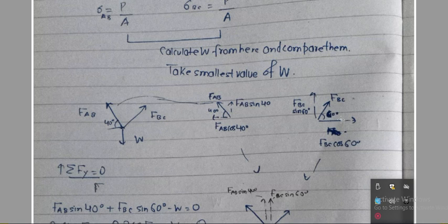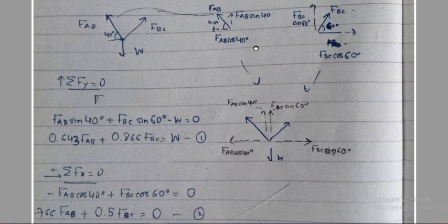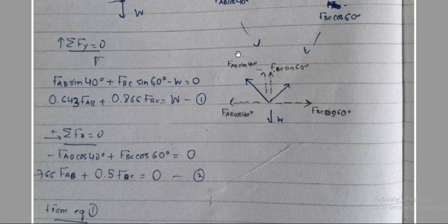If you want to determine the component in x direction, we know that the component adjacent to the angle is going to involve the term cos. So this is going to be FB cos theta, and the other one obviously is going to be FB sin theta. If this is cos, this is going to be sin. If you draw this in one single diagram, we have something like this. These are the FAB, FBC, and all the components in y direction as well as in x direction.